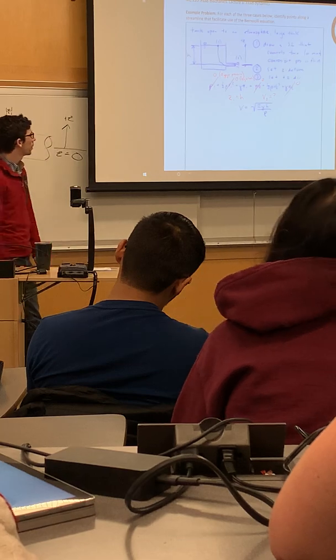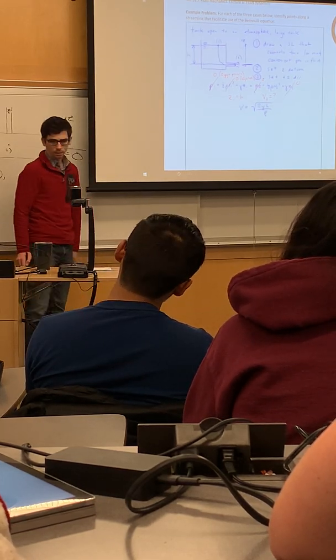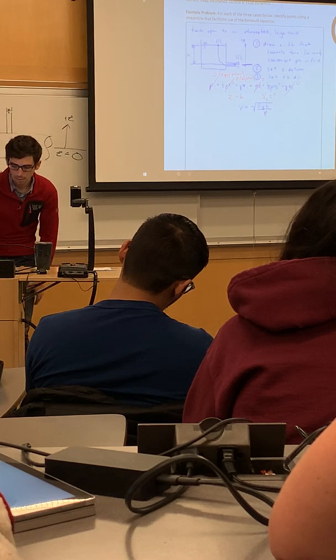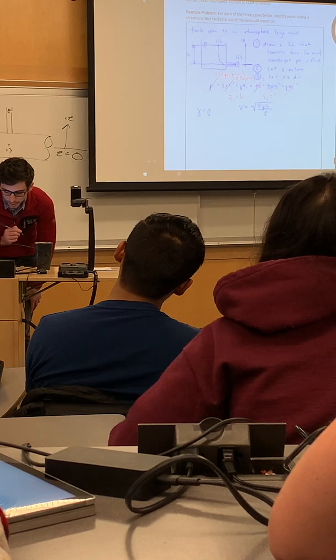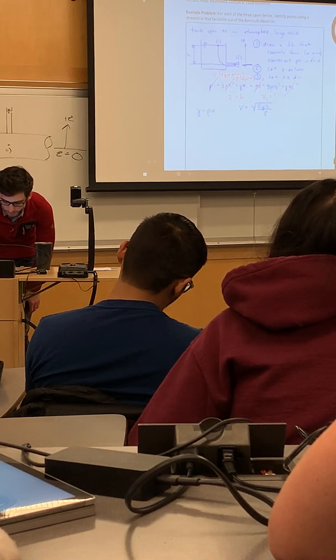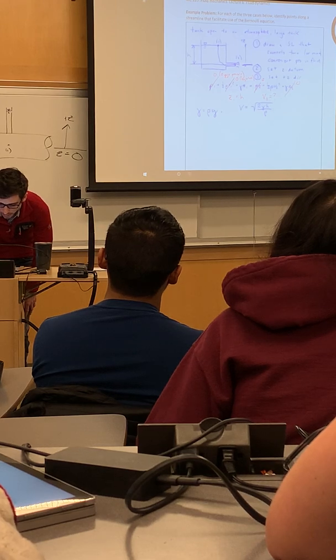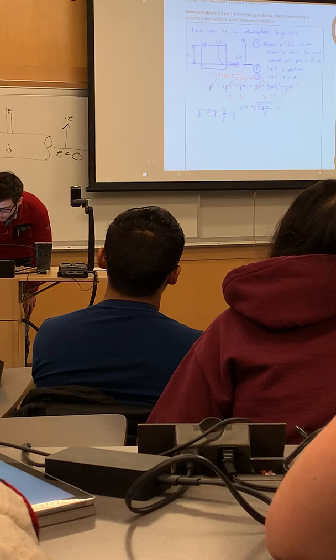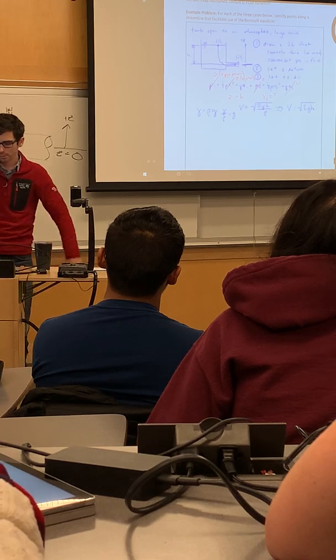And we want to simplify this even further. What's gamma over density? We know a specific weight is, how does specific weight relate to density? Gravity, yeah, exactly. So if we were to just simply rearrange this, specific weight over density equals gravity. So this simplifies to V equals the square root of 2GH.